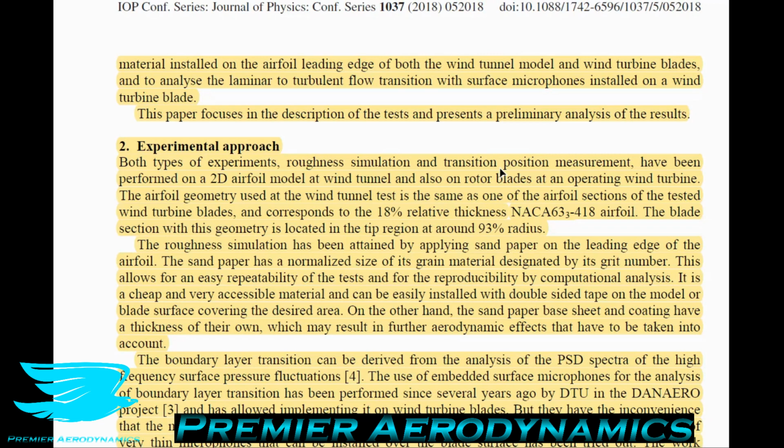But also, you don't want to produce as much lift near the wingtip, for similar reasons as for an airplane, because you'll get greater losses there. So by changing the airfoil profile, you can increase the efficiency and the effectiveness of the wind turbine in total.